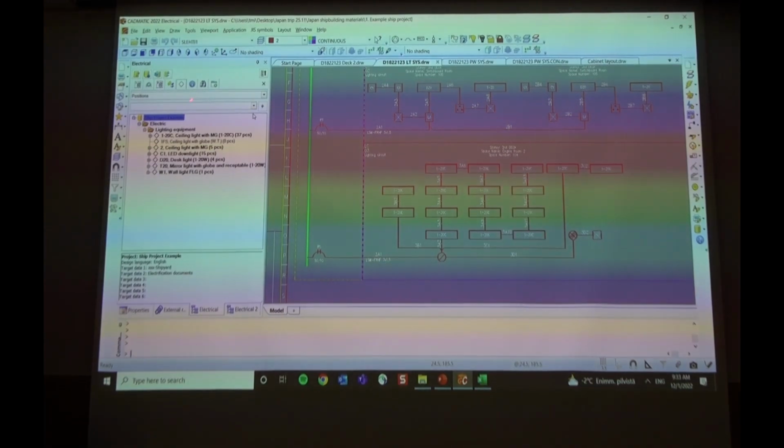We also have this project tree, which can visualize the amount of equipment, currently of the light fixtures, for example. So we have this one, 37 pieces, and these, 0 pieces. We want to change this circuit's light equipment to this 1FS ceiling light with globe. We jump to the database.